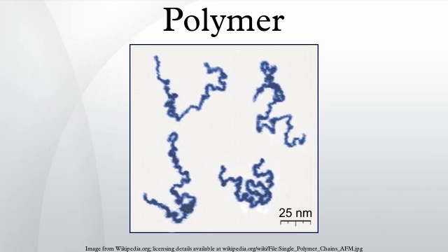Chain length. The physical properties of a polymer are strongly dependent on the size or length of the polymer chain. For example, as chain length is increased, melting and boiling temperatures increase quickly. Impact resistance also tends to increase with chain length, as does the viscosity, or resistance to flow, of the polymer in its melt state. Melt viscosity is related to polymer chain length Z roughly as Z^3.2, so that a tenfold increase in polymer chain length results in a viscosity increase of over 1,000 times. Increasing chain length furthermore tends to decrease chain mobility, increase strength and toughness, and increase the glass transition temperature. This is a result of the increase in chain interactions such as van der Waals attractions and entanglements that come with increased chain length.